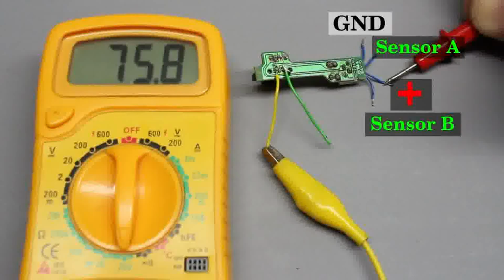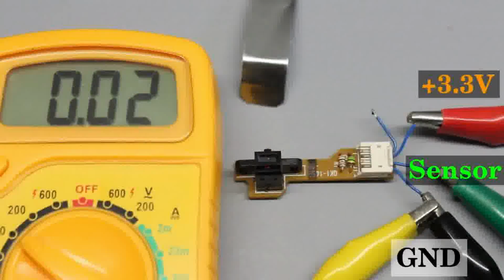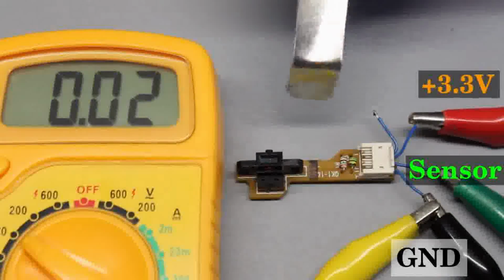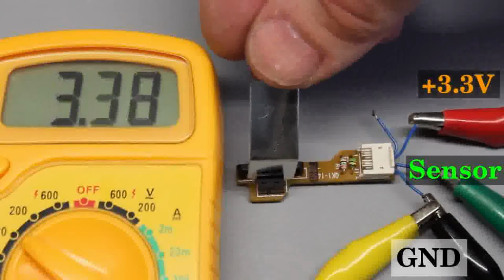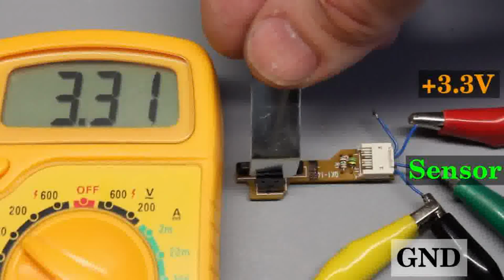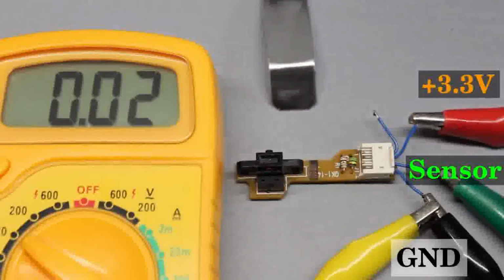As often, a wrong wiring of your sensor unit will destroy that device immediately. So be careful and start testing with 3.3V. As you can see, the device passed the check. You might have recognized that this is the sensor unit used in the previous test as well.